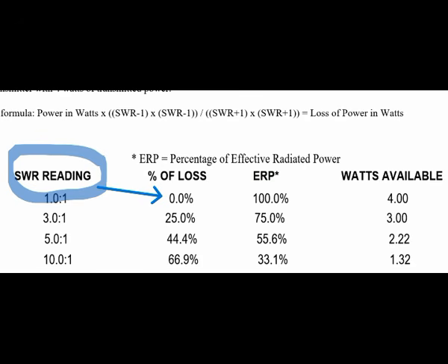The power is not moving from the load back into the cable continuously and just bouncing around in the cable or going back into the transmitter or whatever model people try to put in their minds. That isn't what's happening at all.